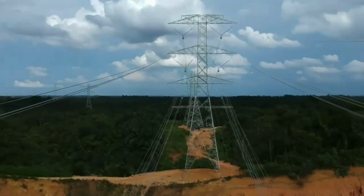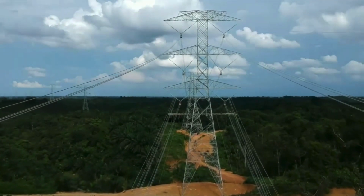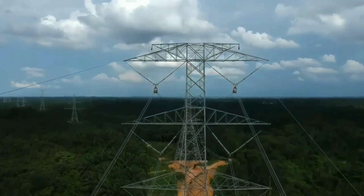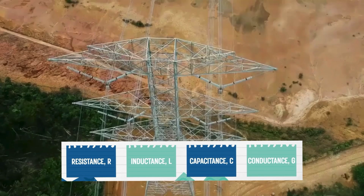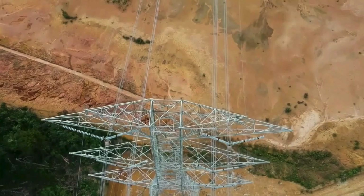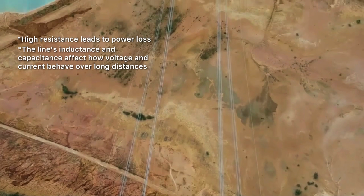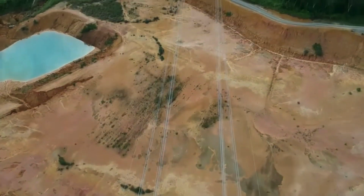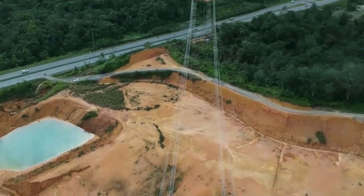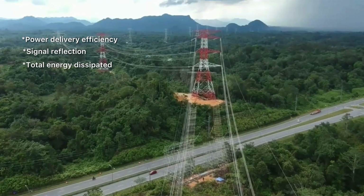One of the most familiar and important applications of transmission lines is in power transmission, which is the high voltage lines you see along roads and across the country. In these long-distance systems, all the transmission line parameters we've discussed, which are resistance, inductance, capacitance, and conductance, play a critical role. For example, high resistance leads to power loss, and the line's inductance and capacitance affect how voltage and current behave over long distances. Engineers use the concepts of characteristic impedance and the propagation constant to analyze how efficiently power is delivered, how much signal might reflect, and how much energy gets lost along the way.